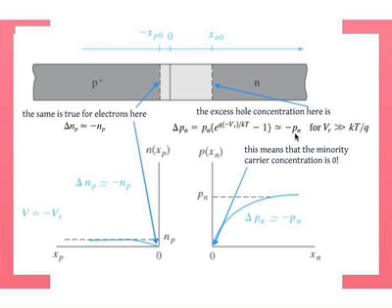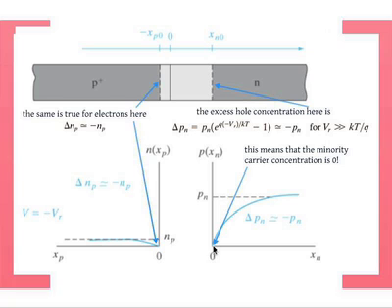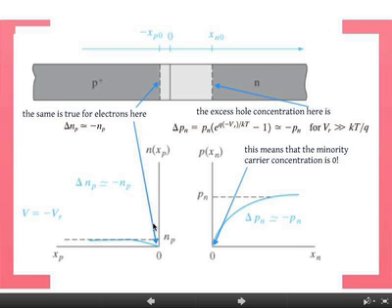So the excess carrier concentration becomes negative, which means the carriers have been lost, they have been extracted away, and the exact number is equal to the equilibrium concentration, which means that the total carrier concentration there is basically 0, right at that boundary. Okay? This means that the minority carrier concentration is 0 right there. Of course, which also means the quasi-Fermi levels have to split and all the same thing that happens in the opposite direction. Okay? Same thing for the electrons in the p-type.